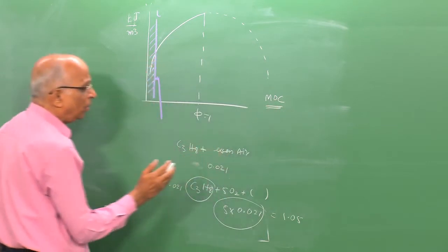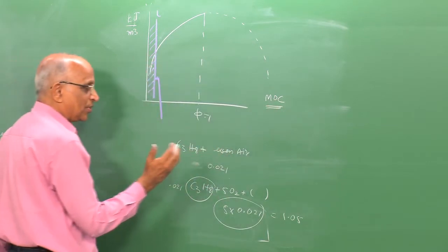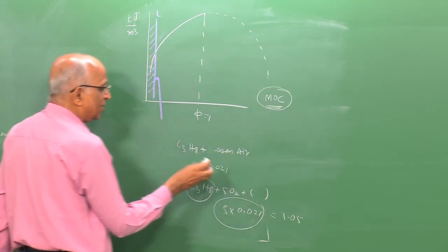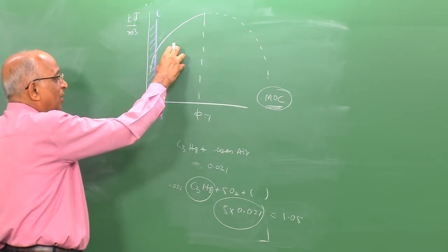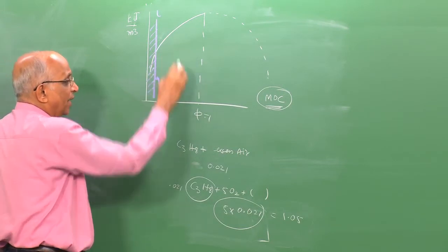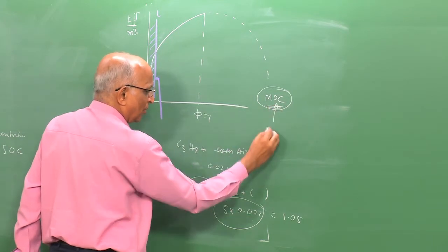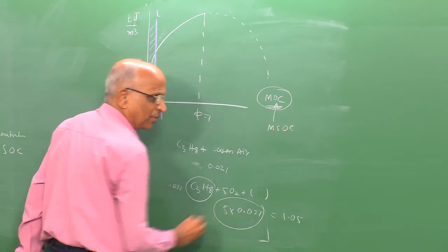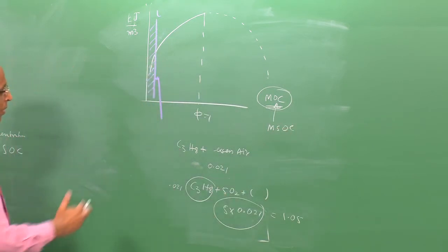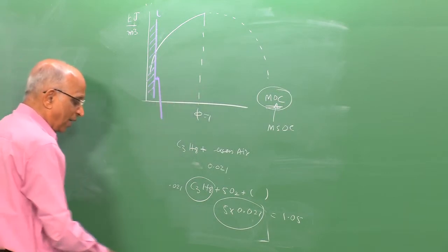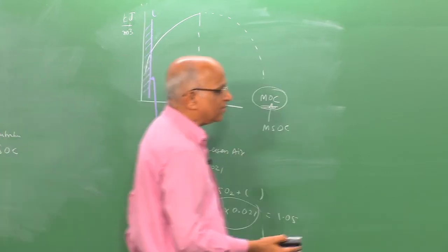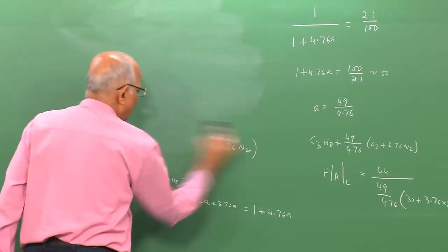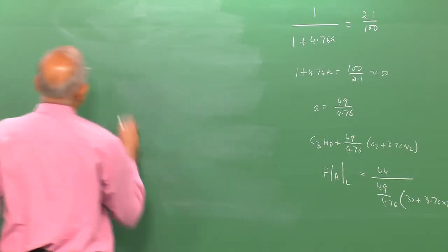It is a very useful tool used in industry to add the right amount of inert gases. That means you find out how much oxygen is available in a gas and how much inert is added to bring it down to the minimum oxygen concentration, which we also call the maximum safe oxygen concentration. Let us do one more problem to clearly illustrate how we calculate this. Let me take the example of the minimum oxygen concentration for, let us say, kerosene vapor.